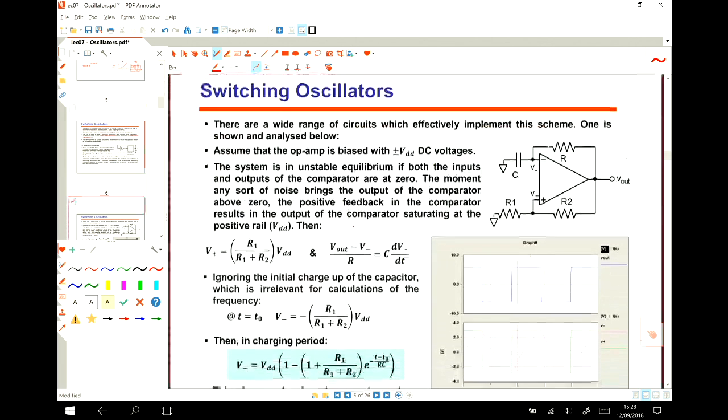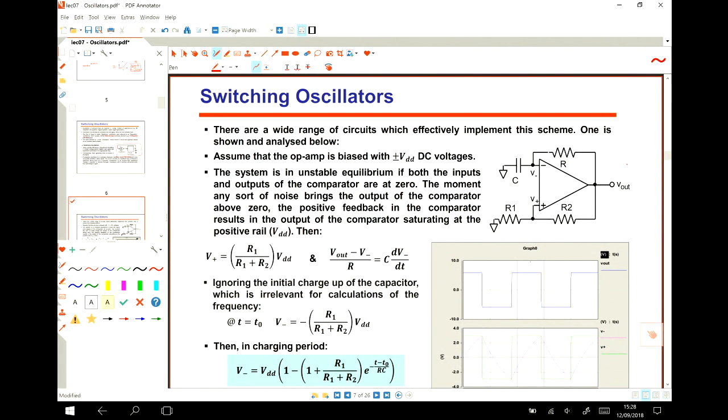So I will explain this here, maybe by equations it is easier. The main nonlinearity of this device is that it is going to get saturated at the output by its VCC and VSS. I mean, the nonlinearity of this device comes from the fact that the output of this device cannot reach more than the VCC or go below the VSS. So this is the nonlinear situation. And then by using, or abusing, this nonlinearity, we can make an oscillator.